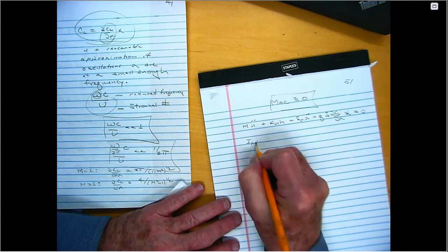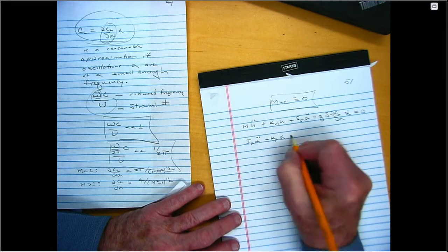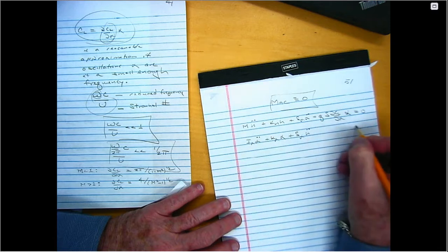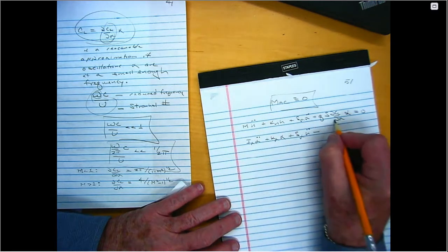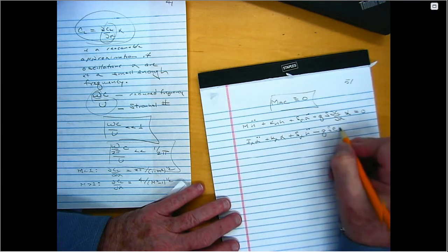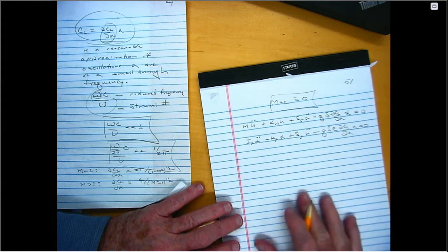Then I alpha alpha double dot plus K alpha alpha plus S alpha h double dot is equal to plus M sub y, so it's minus M sub y, which is minus Q, this is minus the lift times e, right? So it's minus Q S e dCL/d alpha alpha equals 0.